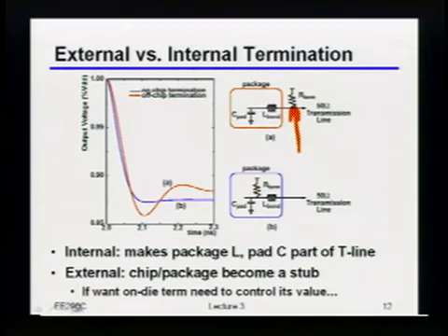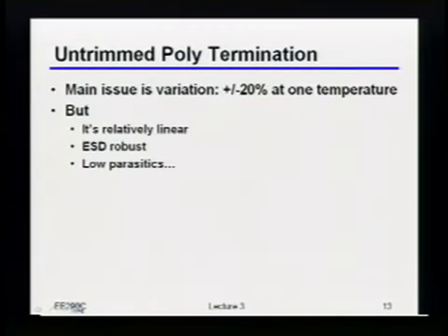Okay? So the simplest thing that indeed is pretty common is if you want to do a termination resistor, you just say, okay, screw it. I have poly resistors in my process perhaps, which of course just looks something like this, where these are just the contacts. And I may just have a slab of unsilicided poly.